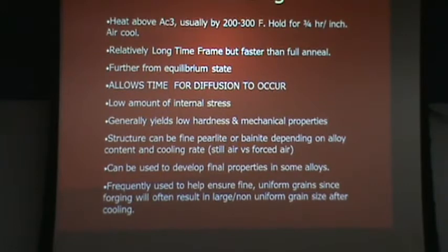And so you'll still usually get a pearlitic structure, but in this case your pearlite will be a finer pearlite. You'll have a little bit higher hardness in comparison with a fully annealed component. Your tensile strength will be a little bit higher. We see that in certain situations customers use parts in the normalized condition.